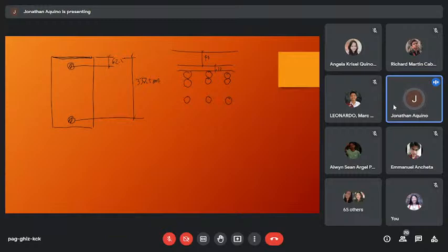So by Varignon's theorem, see if we take this one or here as your reference point, okay? So this one will have a lever arm of 12.5, kasi 25 siya, di ba? Then this one will have a lever arm of 25 plus 12.5. We have 37.5.